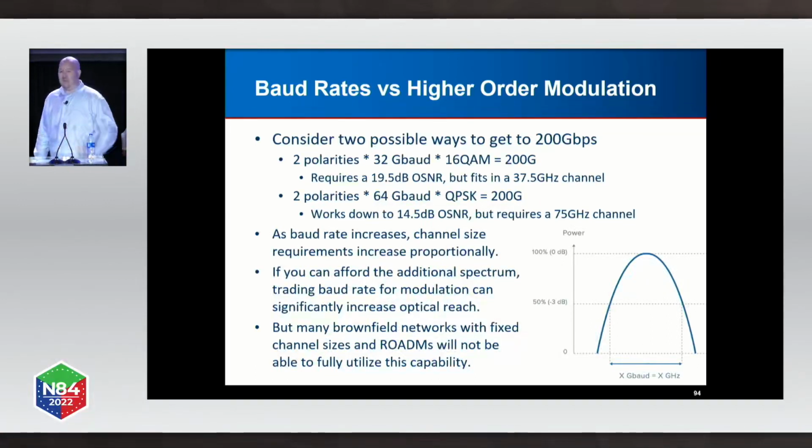For example, a new thing that's coming up that everyone's going to want is 400 gig ZR. There's a talk about it after. Cheap, beautiful, plugs right into your router, it looks great. Some things people don't know about 400 gig ZR. It's a 59 gigabaud signal. It needs a very wide passband mux. Your brownfield muxes will not do it, period, full stop. You need amplification, you need all kinds of other stuff too, but it is becoming more and more the direction that things are going, that we're doing these higher gigabaud signals, and you need new muxes to accommodate that.